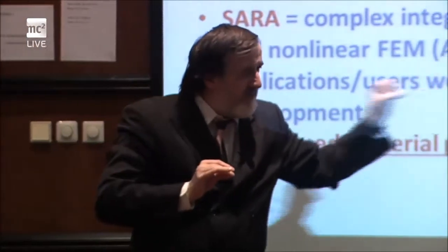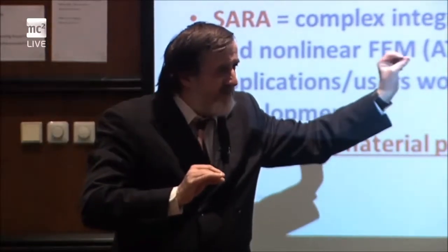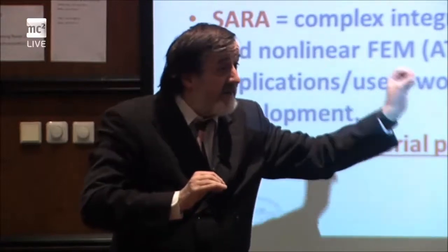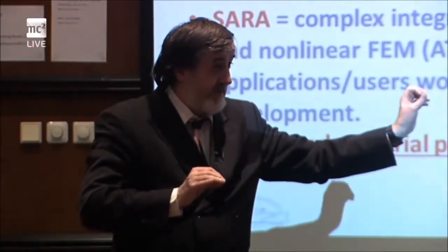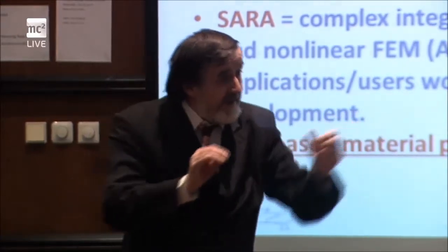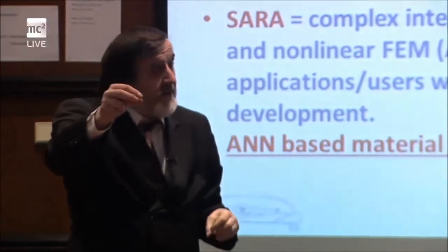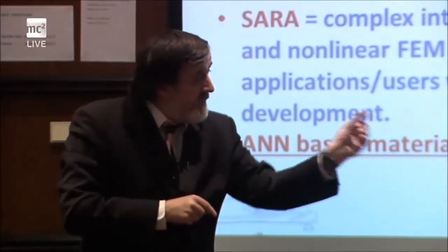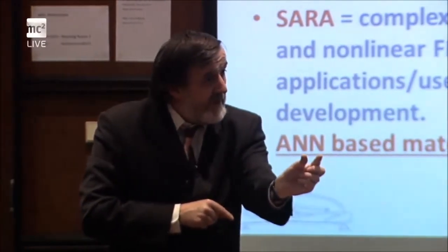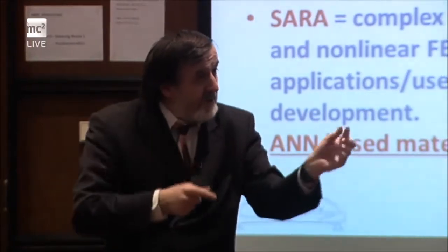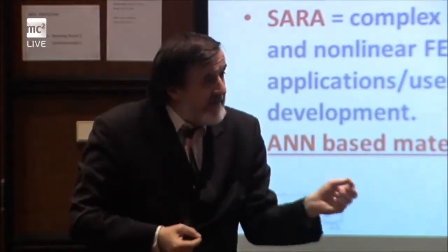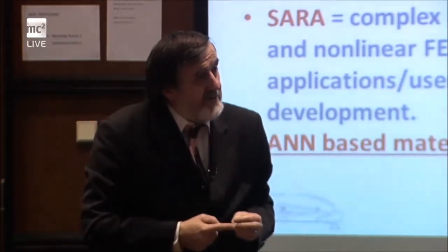And I pick up what dynamic people measure on the bridge, real experimental data of eigenfrequencies and eigenmodes, right? I put them to the network, and the neural network will tell me, well, here is a stiffness like this, another stiffness like that. And this is how the location and level of damage is hopefully assessed based on this procedure.